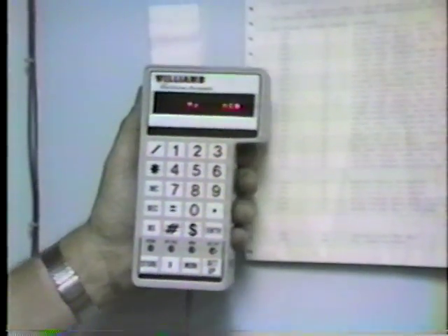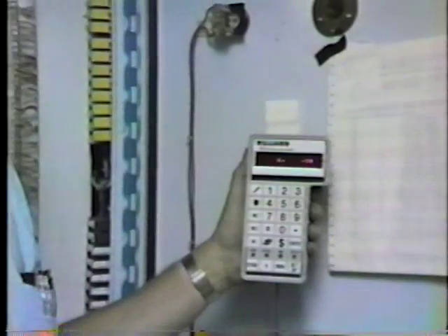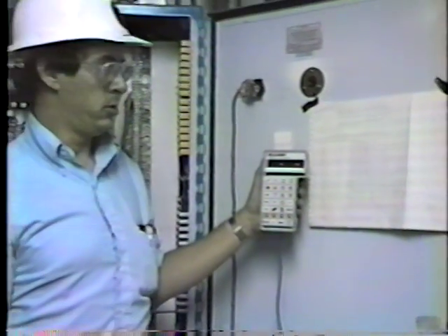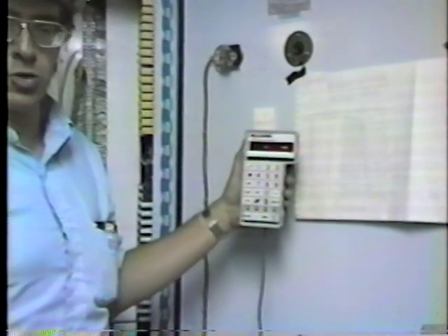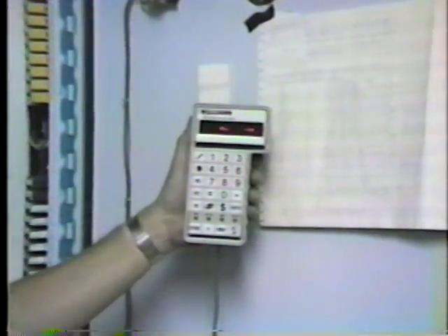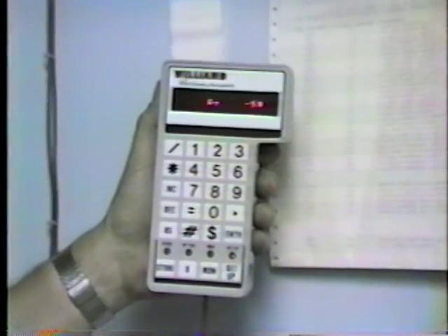All right, would you go to the next one? We're not using number 5 anymore, so we leave it at 0. 5 is not used. 6, spinner speed percent maximum decrease. And how's that used, Jim? That sets the rate limit to drop the spinner speed. We allow the spinner speed to drop as much as 5% per second.